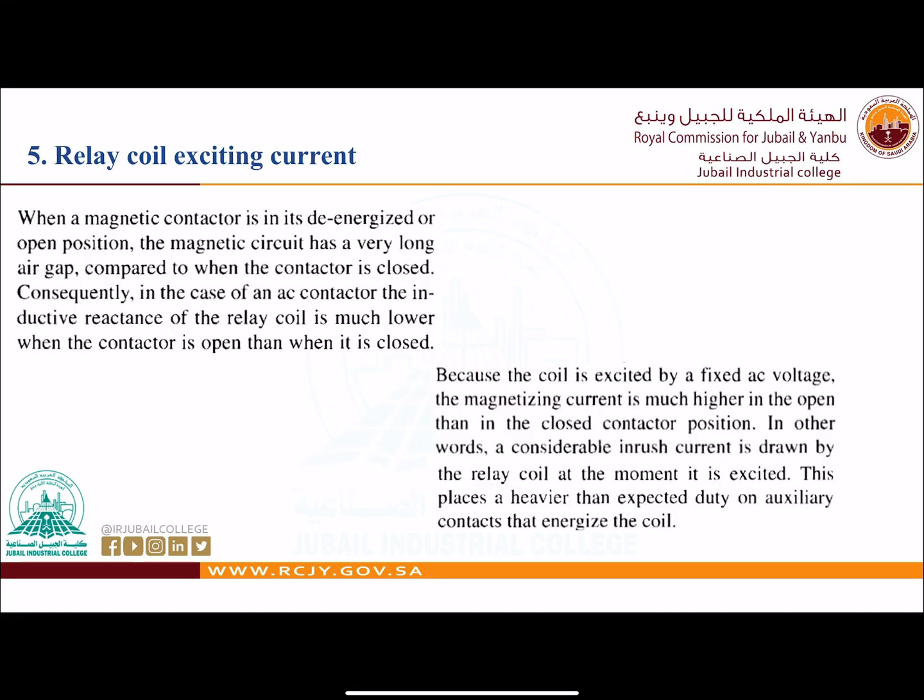When a magnetic contactor is in its de-energized or open position, the magnetic circuit has a very long air gap compared to when the contactor is closed. Consequently, in the case of an AC contactor, the inductive reactance of the relay coil is much lower when the contactor is open. Because the coil is excited by a fixed AC voltage, the magnetization current is much higher. So if we energize the contactor, if we energize this coil,